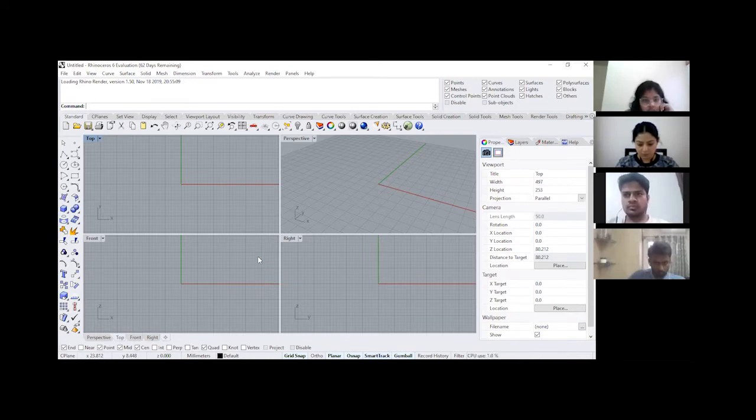Right off the bat, it's different from SketchUp, because over there you have just one window, which gives you a perspective projection, or a two-point perspective, or a parallel projection, whatever you select. Whereas here, in the same 3D environment, you get multiple projections in multiple viewports. That makes for a much more interactive and easier scenario for modeling also.